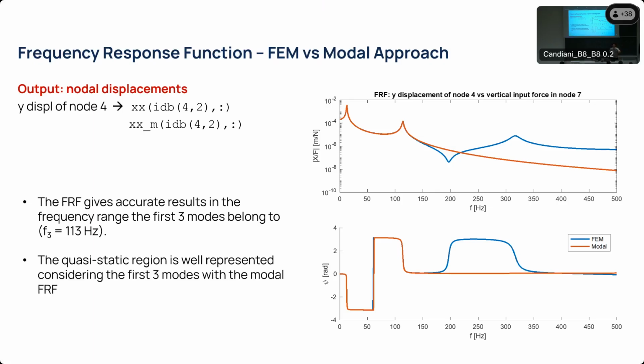Maybe you're not interested in the 11,000th mode shape at 500 Hertz of one of the cables, because that's not something interesting if you're looking at the value of the lateral displacement of the deck of the bridge at 2 Hertz. So that is information you can discard.